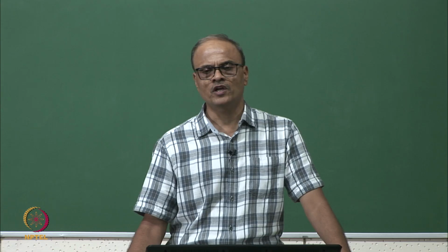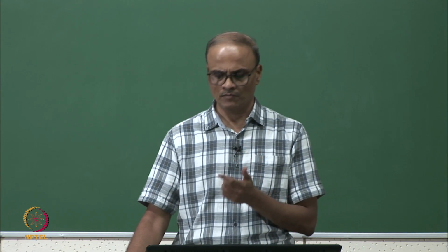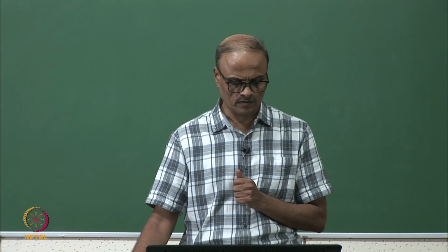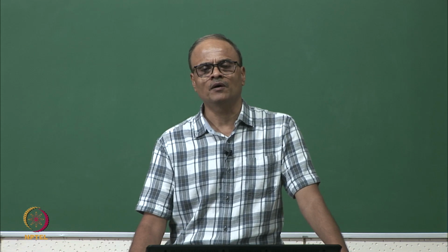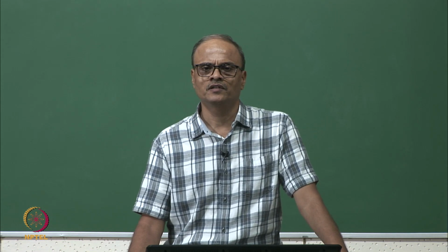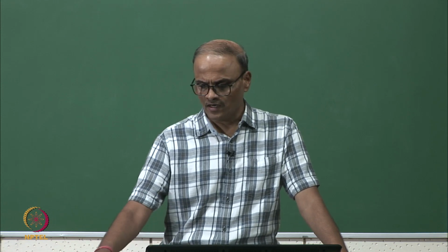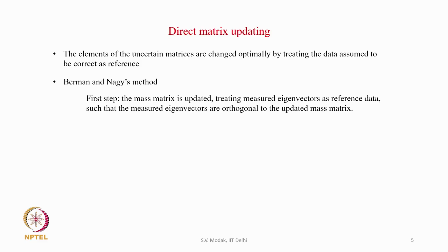In this lecture we are going to focus on one of the direct matrix updating methods, which was proposed by Berman and Nagy. We will refer to this as Berman and Nagy's method. This method essentially updates the mass and stiffness matrices, treating the measured modal data as reference data, and this is done in two steps. In the first step, the mass matrix is updated treating measured eigenvectors as reference data, subject to the constraint that the measured eigenvectors are orthogonal with respect to the updated mass matrix.